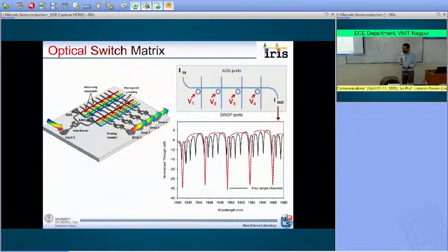How can we do that? Well, we can do it by using the heaters. So what we do is inject a proper current in each one of those microring resonators so as to be able to align all the microring resonators to the same wavelength. And this is the outcome. So you see now that we were able to align all those microring resonators together.